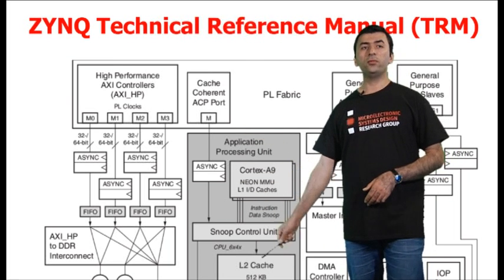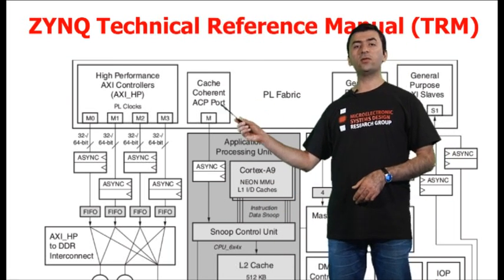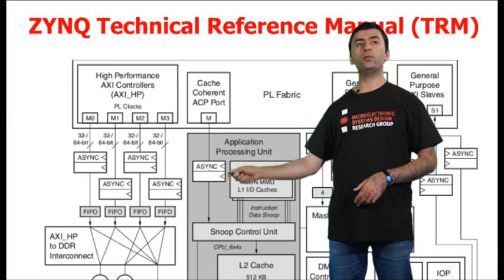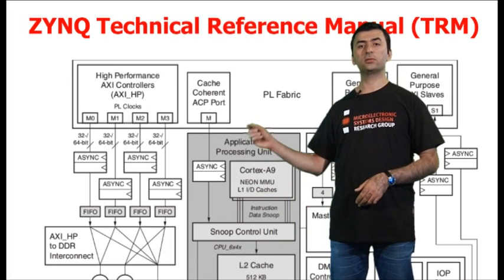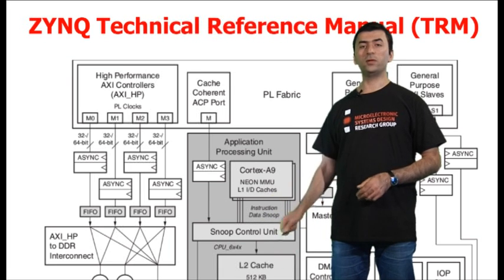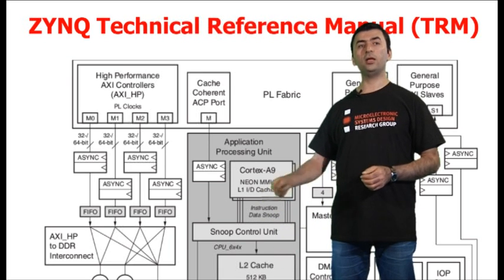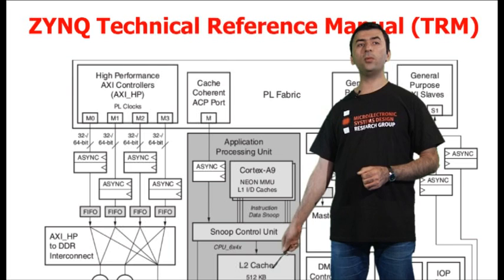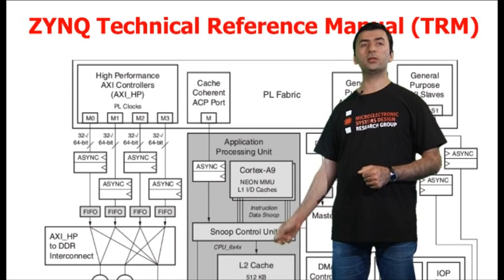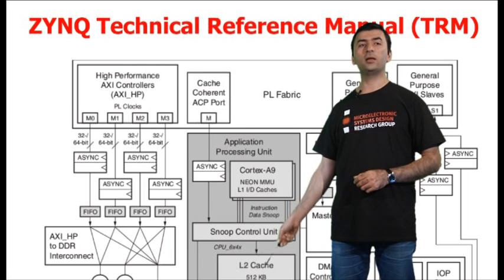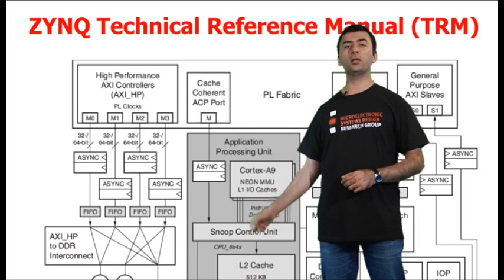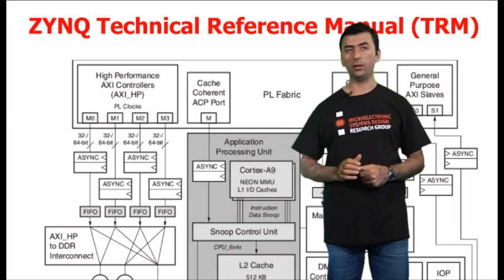This allows the AXI plug that you have here to perform coherent transactions to the memory space of the CPU. And if the data instance is available here on the L2 caches or the caches of the CPU, the transaction will be responded to directly with the data available here.